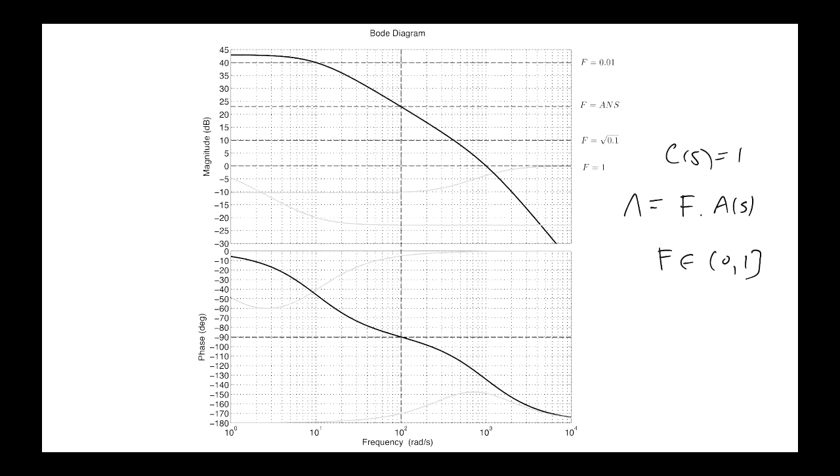You can see that there are the two poles in the op-amp transfer function, right? One pole at a lower frequency that creates minus 90 degrees of phase shift, right? And then another pole at higher frequency that gives you another minus 90 degrees phase shift, over a higher range of frequencies now. All right, so this is just what the phase plot of A looks like. Multiplying by F, which is a positive number, is not going to change the phase plot, right? Because the phase of F is just 0.